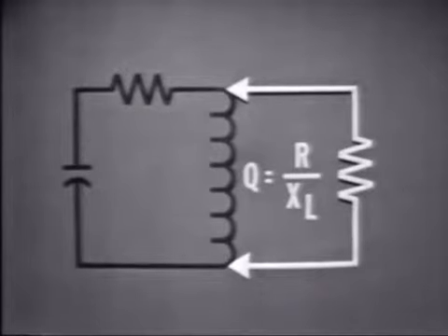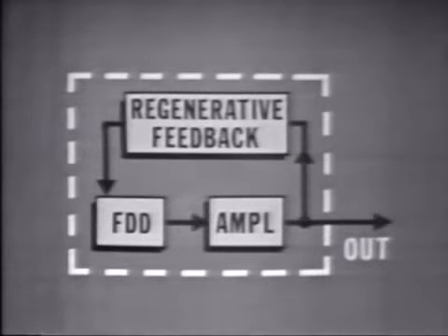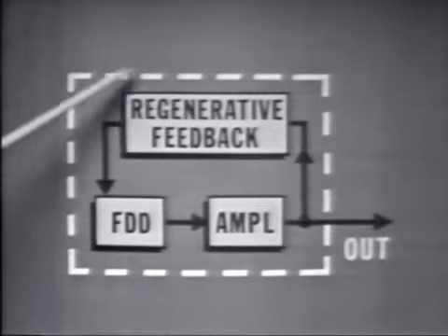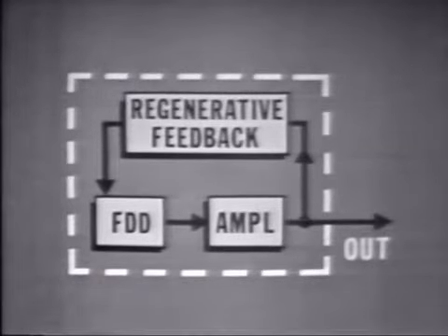In other words, the amplifier connected to the frequency determining device should offer maximum impedance to the tank. Even then, there will be some energy loss to the external load, which must be regained by increasing the feedback. Now, because loading and power surges can cause shifts in amplitude and frequency, the oscillator stage is usually isolated from the rest of the equipment by special amplifiers or other circuits. Now, the exact kind of isolation depends on the particular application or use of the oscillator.